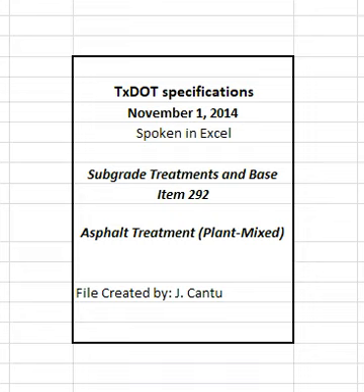4.2.1 Storage and heating of materials. Do not heat the asphalt binder above the temperature specified in Item 300, Asphalts, Oils, and Emulsions, or outside the manufacturer's recommended values. On a daily basis, provide the engineer with the records of asphalt binder and hot mix asphalt discharge temperatures in accordance with Item 320, Equipment for Asphalt Concrete Pavement. Unless otherwise approved, do not store hot mix for more than 12 hours or for a time period less than 12 hours that affects the quality of the mixture.